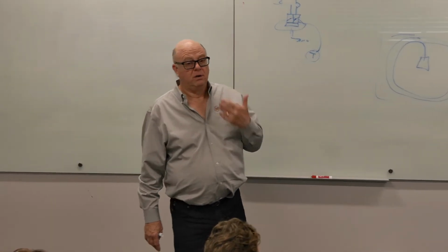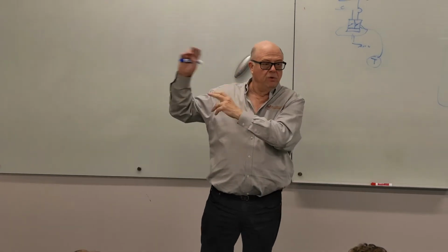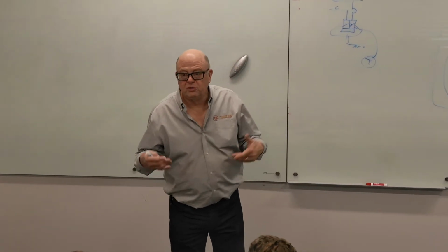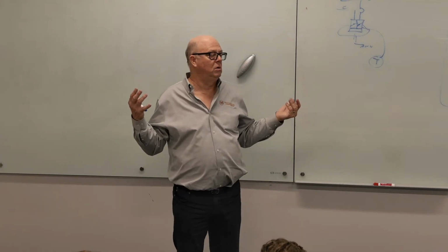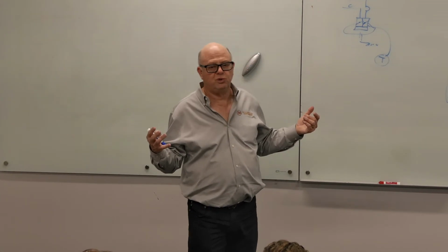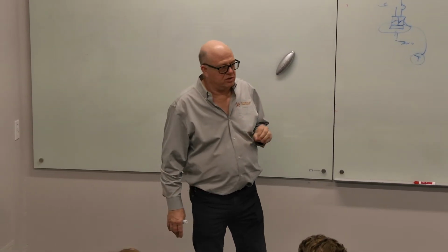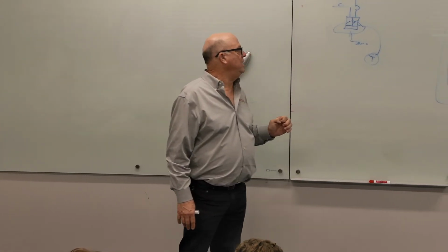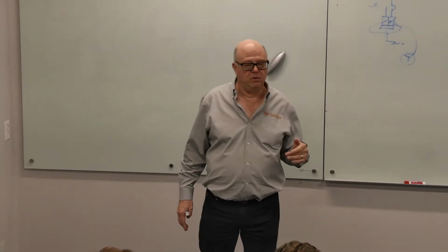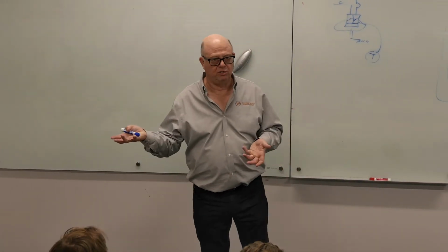And so the CEC thought we were going to see 4-pipe fan coils and dual duct VAV. Initially, I want to say those were the two prescriptive solutions that you didn't have to do anything for. Now they're not the lowest cost systems. And you could even argue that they're not even the most efficient, maybe, depending on your situation.